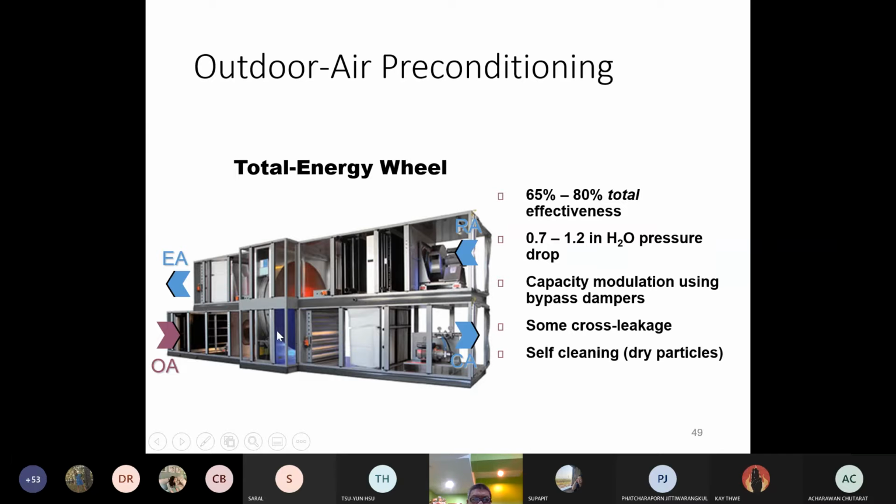When it's colder by the exchange through the energy heat wheel, it will have a better temperature, and it passes the pre-filter and medium filter and is put into the building and into the duct. So after it has been put into the building, after passing so many occupants, then it is returning.